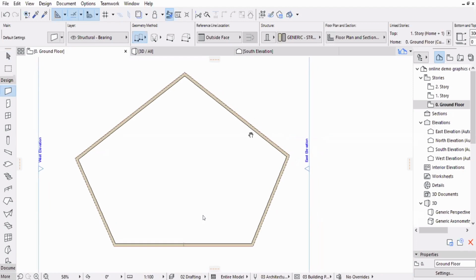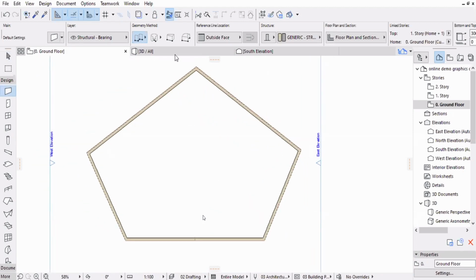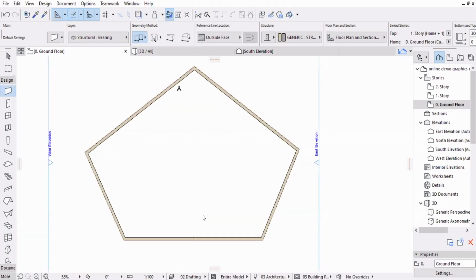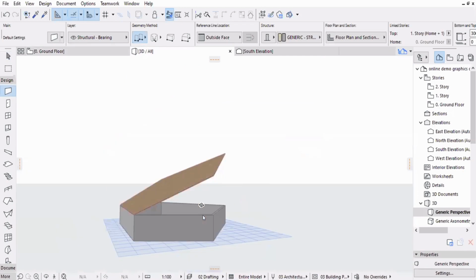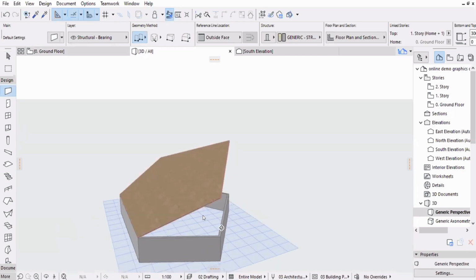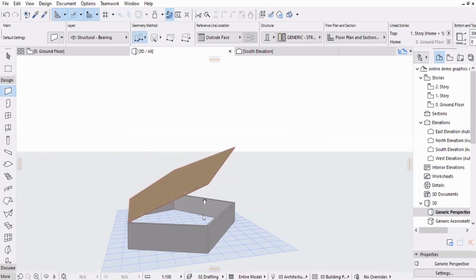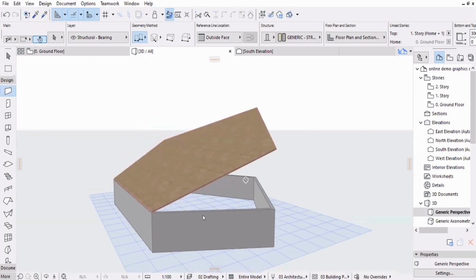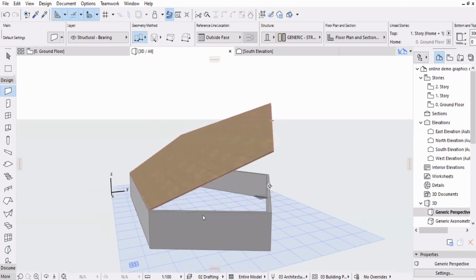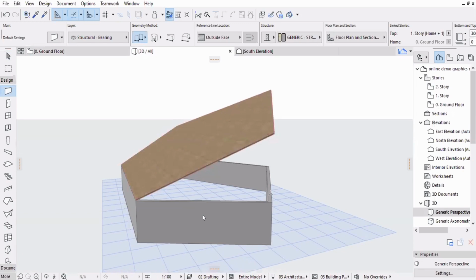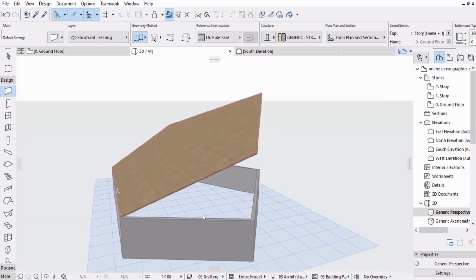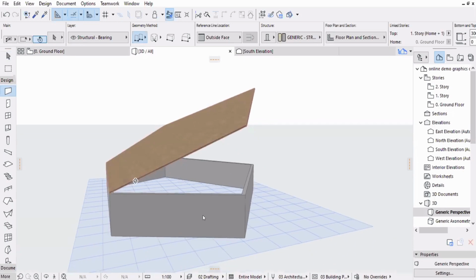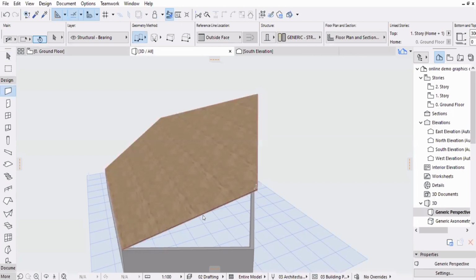We can do either of the things. First, we can draw the walls higher first and do the overhang next. Yeah. But I would suggest to do the overhang first and then draw up the walls, because there is no direct tool in Archicad where you can directly extrude these walls up to exactly the underside of the roofs. But instead, there is a two-way. There are a few steps involved in this.